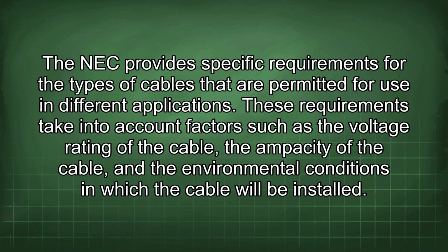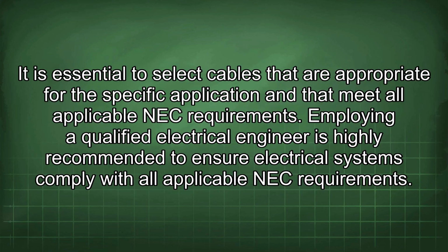The NEC provides specific requirements for the types of cables that are permitted for use in different applications. These requirements take into account factors such as the voltage rating of the cable, the ampacity of the cable, and the environmental conditions in which the cable will be installed. It is essential to select cables that are appropriate for the specific application and that meet all applicable NEC requirements.